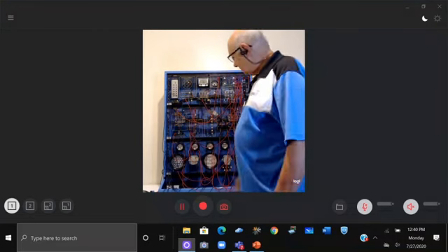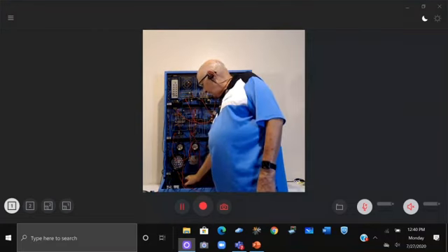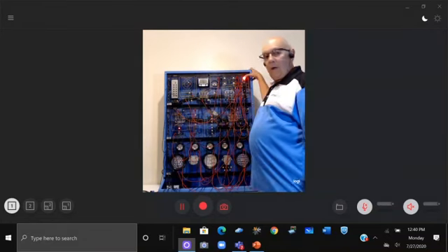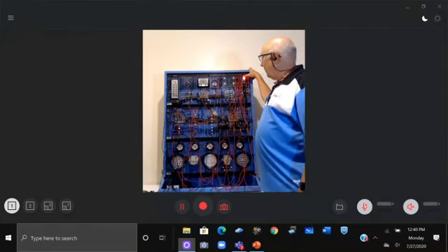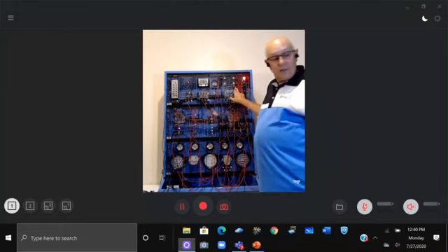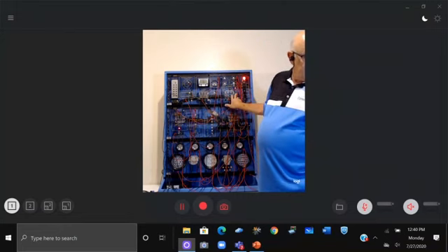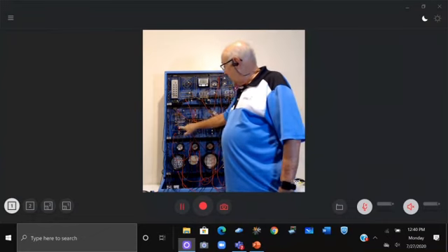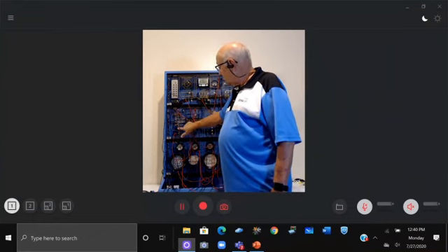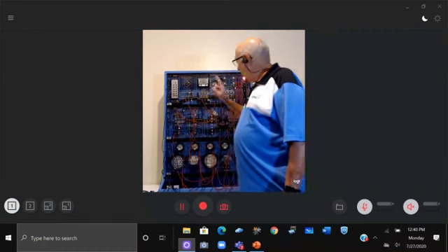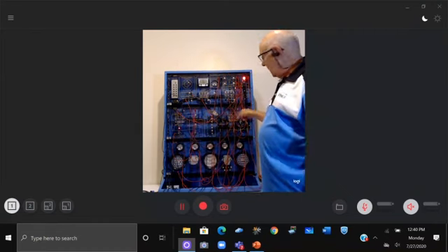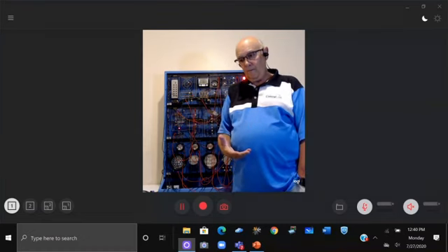So then the next thing I tell students is, okay, turn on the power. Now, when we turn on the power, we have, first of all, a power light. And then second of all, I'm not sure you can see this, let me block it. Okay, the input module is on, light is on, and the engine control module is on. But the instrument cluster is not on, and the output module is not on.